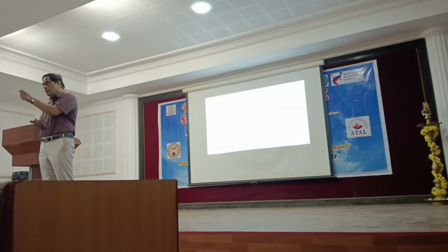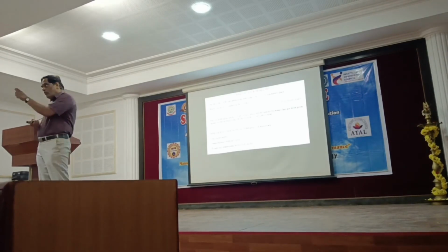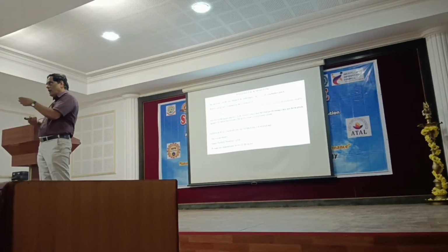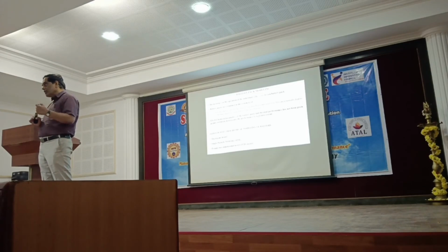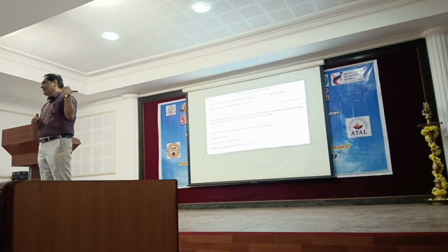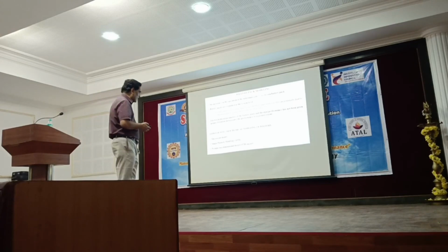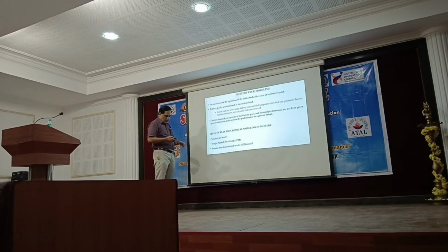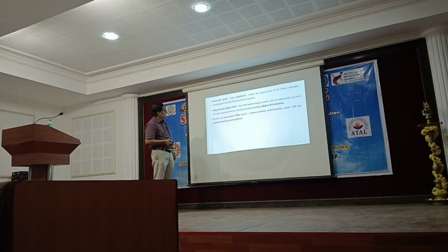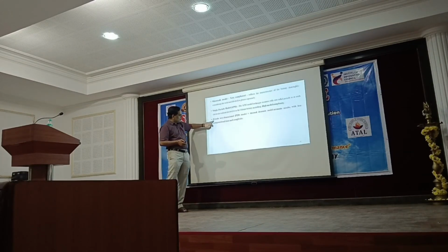It all finally boils down to internally how the lithium ions are moving back and forth, what speed they can move, and how much energy they have. All things come under thermodynamics and kinetics. The thermodynamic properties and kinetic properties are all used to do simulation for SOC, and to do simulation for charging of the battery pack. This is the pseudo two-dimensional model, which accounts for all electrochemical principles in terms of both thermodynamics and kinetics. Both are complex, but they are much more useful, and less computationally intensive.